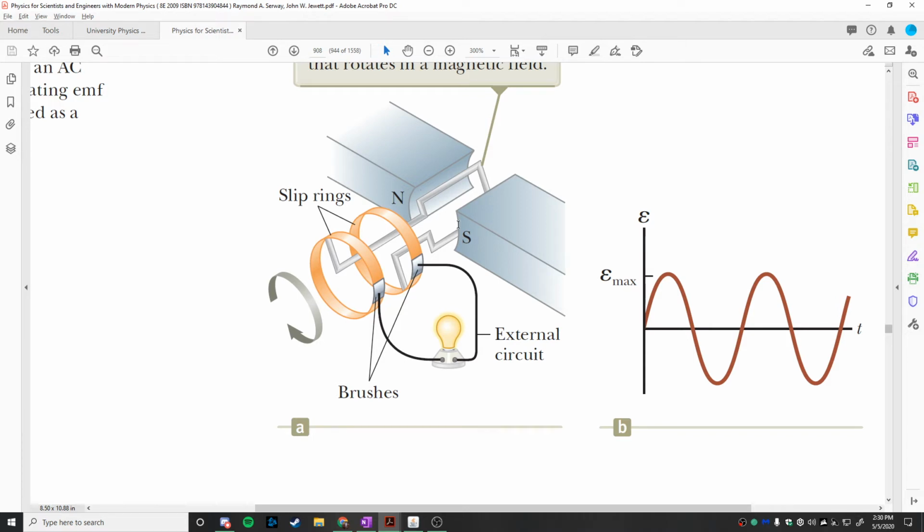It has the effect of slowing it down, below what you might expect to get out of it, if that makes sense. So maybe you expect it to be rotating at 120 RPM, but when you try to turn it up to 120 RPM, you get this huge amount of resistance. And that resistance that you're feeling is effectively back EMF. So instead of actually spinning at 120 RPM, maybe it spins at 88 RPM, where it finds a balance.